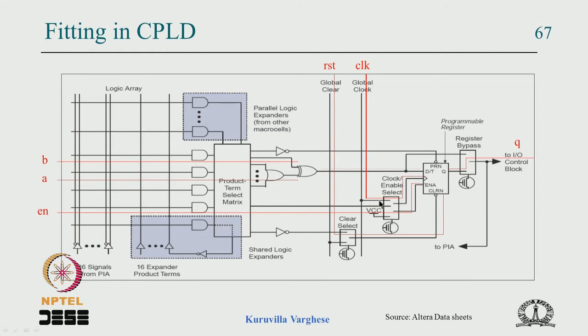So this switch is programmed for the clock, and you have A and B pins, which I am not showing, going to the crossbar switch, and the crossbar output is coming here. A is coming to this AND gate, B is coming to this AND gate, and this particular AND gate goes to one of the OR gate inputs and goes to the XOR gate, and B directly goes to this AND gate and goes to the XOR gate here.